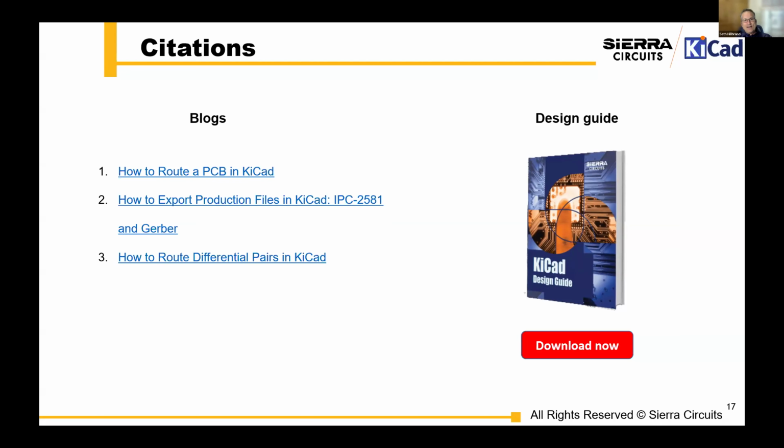So the plugins are going to really depend on what you're trying to do with KiCad. There are some great plugins out there. The interactive BOM plugin is a really good one if you are doing hand assembly, or if you are trying to debug a complex board. That tool can be really helpful. Additionally, there is a plugin called KiVar that implements variants.